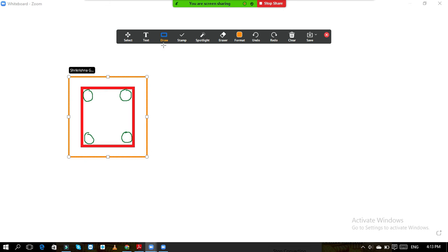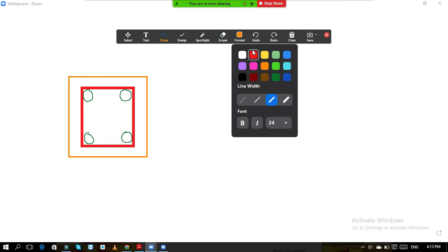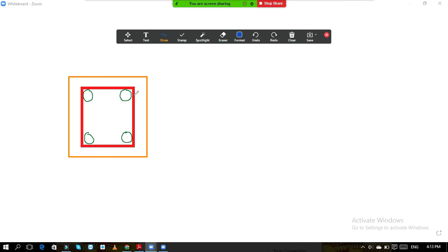So now how to calculate the B1? At top, it should be calculated at top or it should be calculated at bottom. That is the question. So now what I want to tell you is that here, suppose these bars are two bars of 10 mm. Okay. And suppose these bars are two bars of 20 mm. Now we will calculate the B1 at both. Okay. Suppose the clear cover is 25 mm.